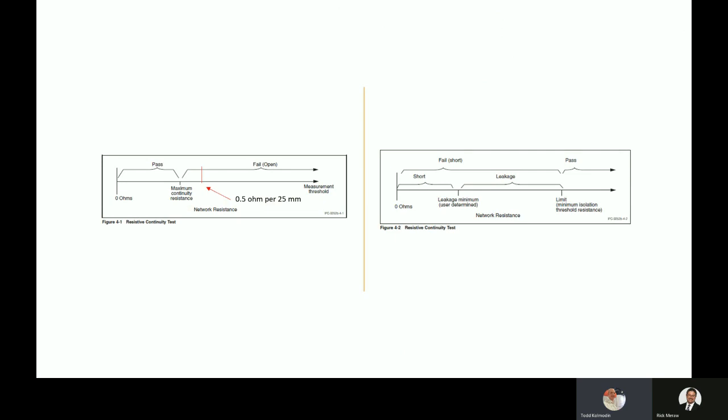And just to go back to Rick's explanation on adjacency, the whole adjacency idea is all working with detecting shorts. The adjacency window doesn't mean anything when it comes to continuity. Continuity is the connection between point to point. So in each performance class or test level, we have different recommended parameters by the group for each level. So we talk about voltage, then we talk about isolation threshold, and we talk about continuity thresholds.